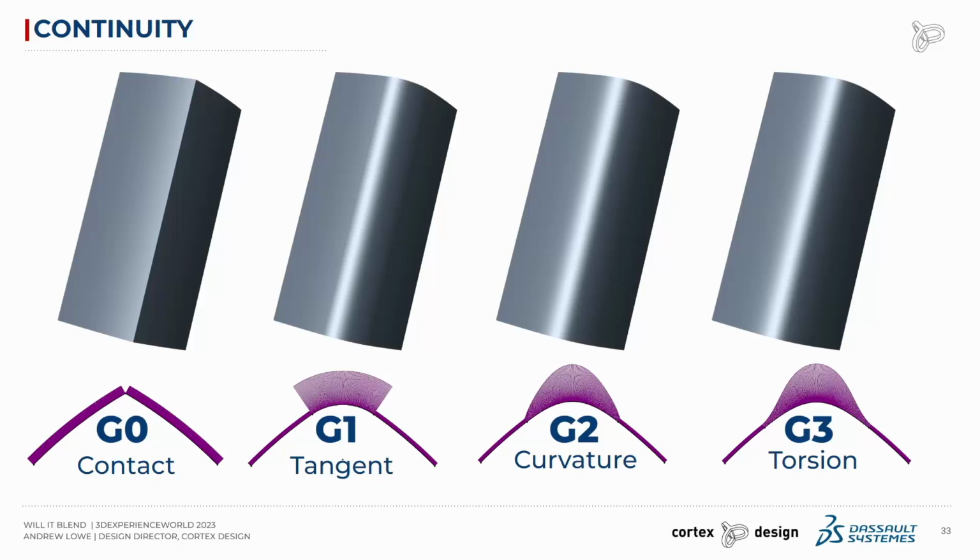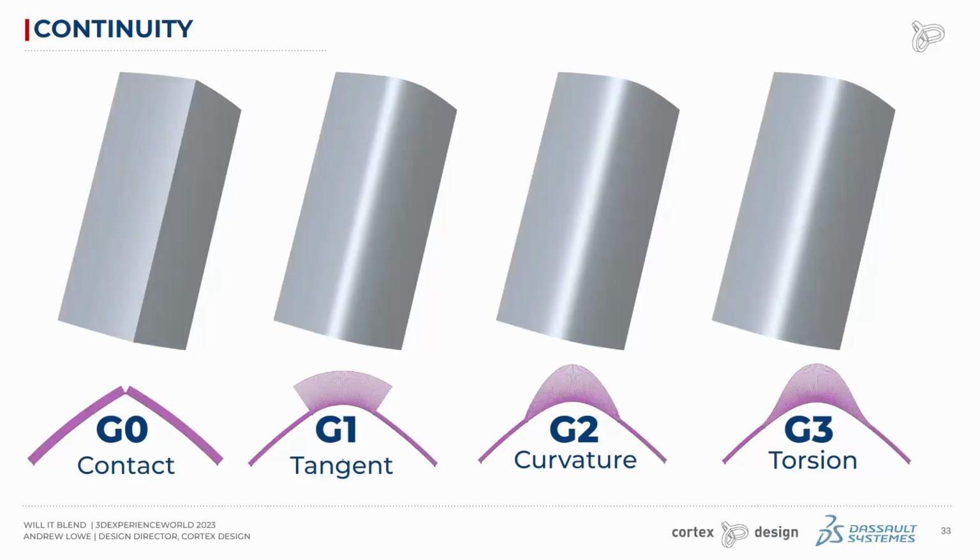It is possible to do in SOLIDWORKS. We'll look at an example at the end of this presentation, but take it with a grain of salt. It is not particularly parametric, and you can get into a lot of unknown rebuild issues and be banging your head against the wall, but it does get you the smoothest possible geometry. So if you are looking for this kind of modeling, I would advise doing it at the end of your creative or design process, where you potentially work with lower orders of continuity and then rebuild or resculpt a model for those higher levels of continuity.